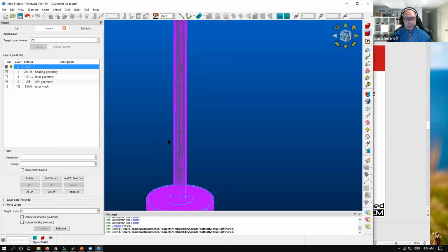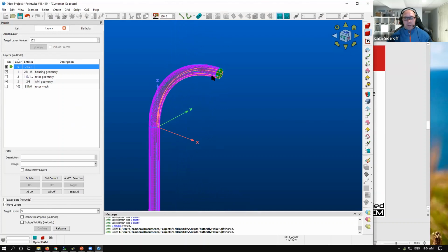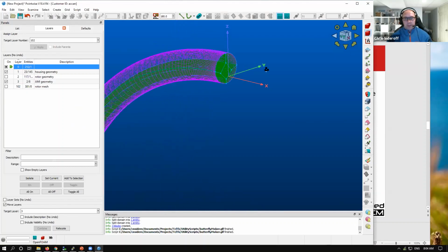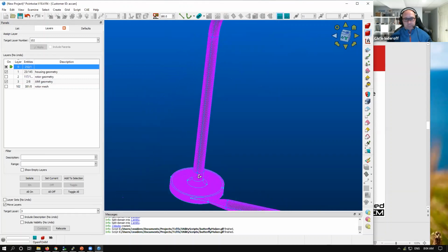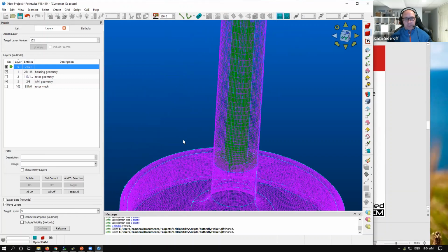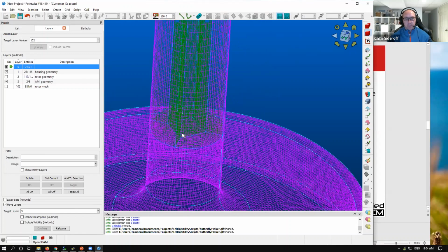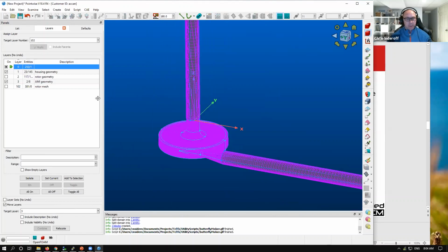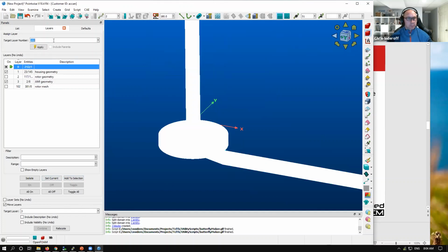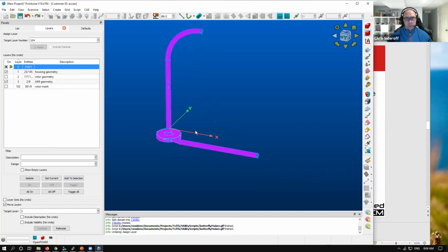All right, so let me go look at this mesh real quick. Now it's kind of clear. We have this 5-block OH topology. This is what we want. So what I'm going to do is take all this mesh I just generated. I want just the inlet region.